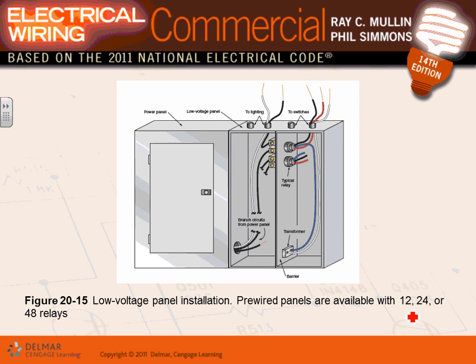Here's how it goes, gentlemen. Here's my lighting. This is my lighting control panel. Let's just say you bring a 20 amp. Here's my 200 amp panel. You take a 20 amp circuit, like we said. You bring that circuit into here. There you go, coming to a relay. Out of the relay it comes out to a lighting fixture. And then, of course, you need to bring a neutral.